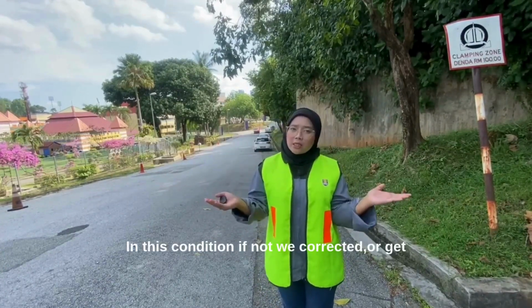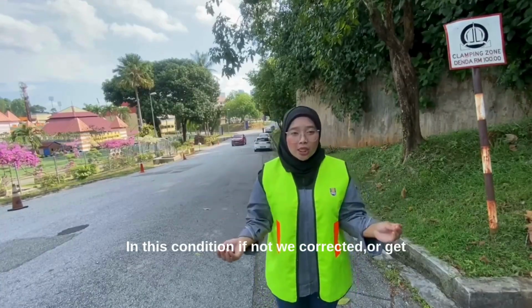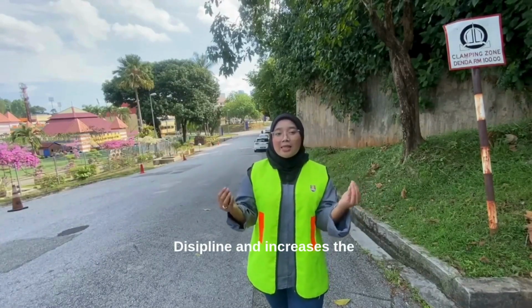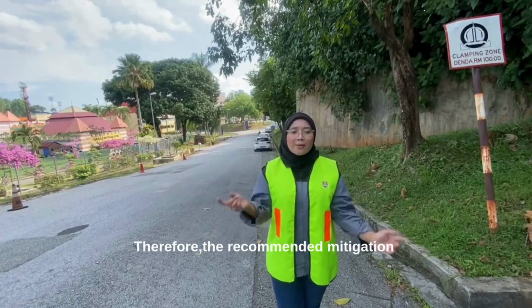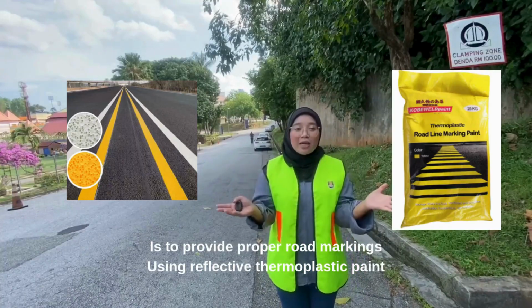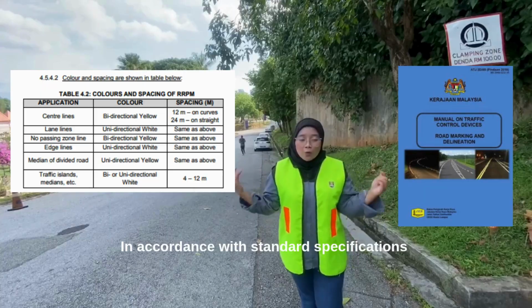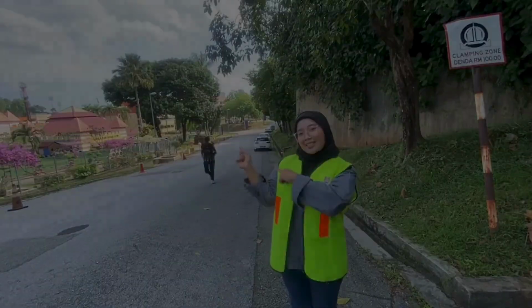In this condition, if not corrected or given any solutions, it may continuously impact driving discipline and increase the likelihood of minor traffic conflicts. Therefore, the recommended mitigation is to provide proper road marking using reflective thermoplastic paint in accordance with the standard specifications to improve visibility and road organization. So we go to the next.